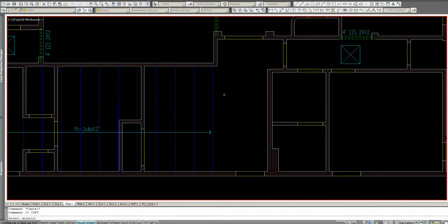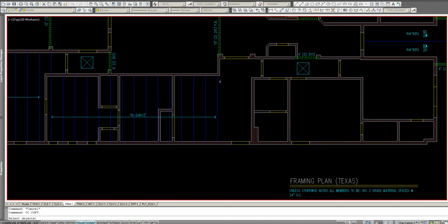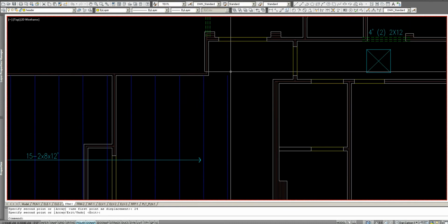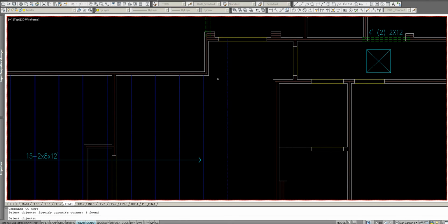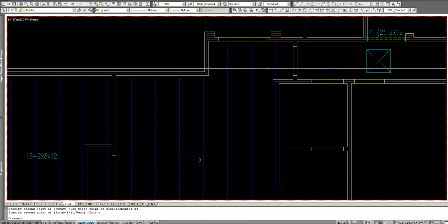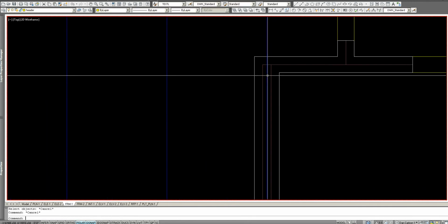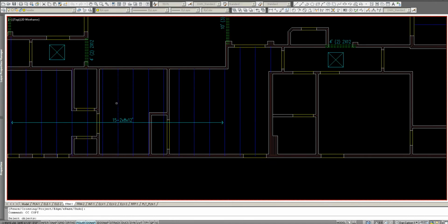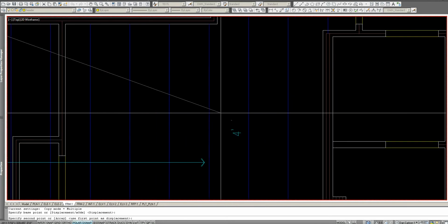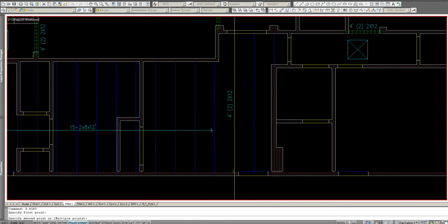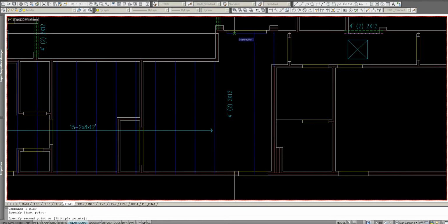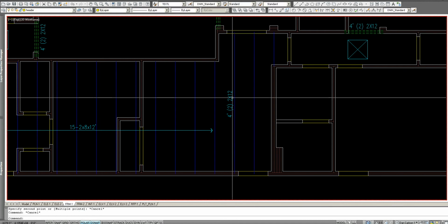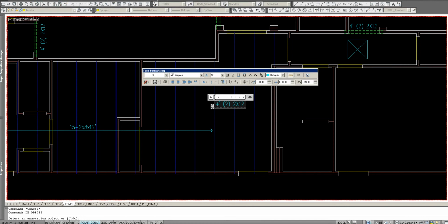Then let's see, starting right here, looks like we're going to go back to having a longer span just for a couple of these. Alright, we don't need that one. Yeah, we can just trim that end off. There'll be a little tiny joist right there. Since there's only 2 of these, I'm not going to draw the arrows. I'm just going to call them out directly. So this one is 14'6", and my 2x10s can go 14'9", so this can be a 16 foot 2x10, just like that.